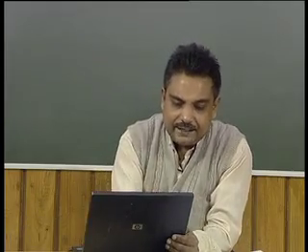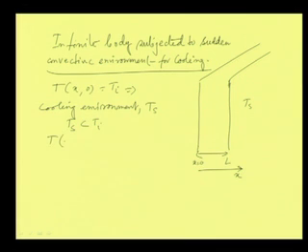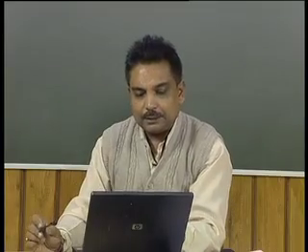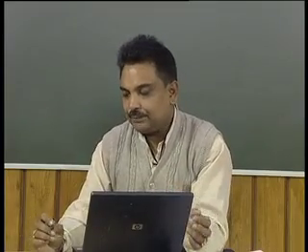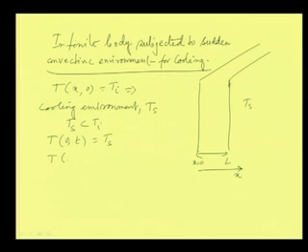Now, according to this, T at x equal to 0 for any time t should be equal to Ts. So, x equal to 0 means the other face, the back side, the temperature of that surface is equal to Ts, and T at x equal to L, for any time t, is equal to again Ts.